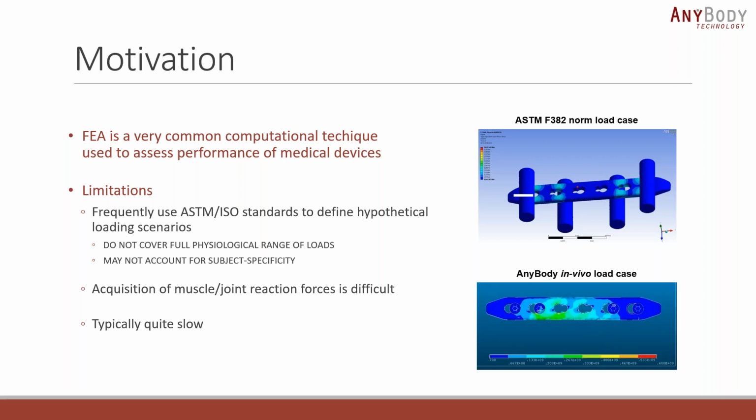When we do structural analysis of, let's say, medical devices, we rarely know the internal loads in the body, and we either rely on available publications which provide us with certain values, or we look at the standards, like, for example, a 4-point bending ASTM load case.